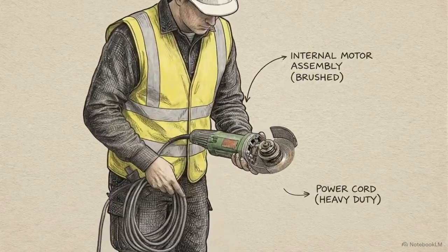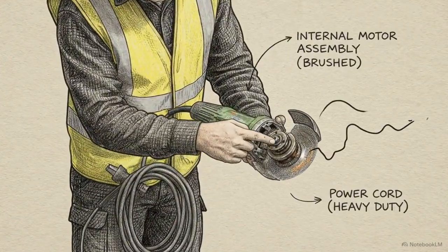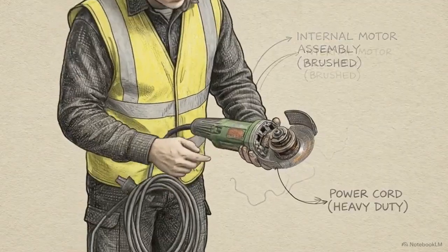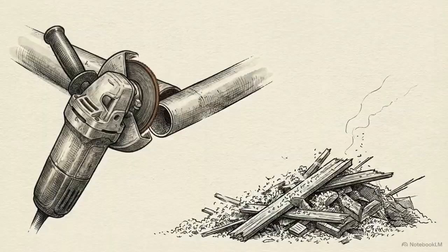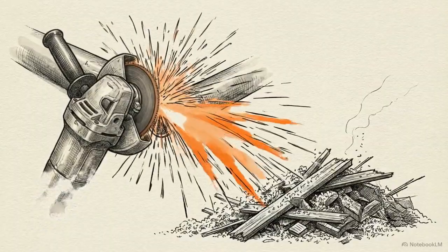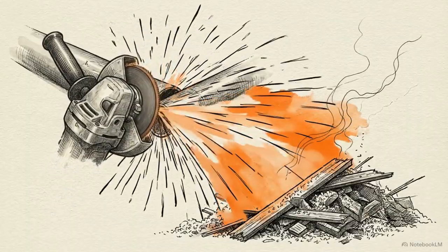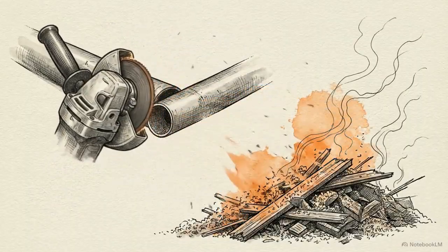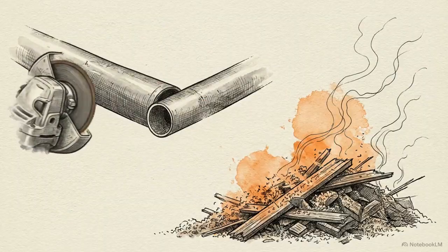Urgent tone, a subcontractor arrives to conduct hot works on a UK construction site. They realize their standard grinder is broken. To save time, they swap it for a different, unfamiliar tool and alter their cutting process on the fly. Within minutes, combustible debris catches fire.